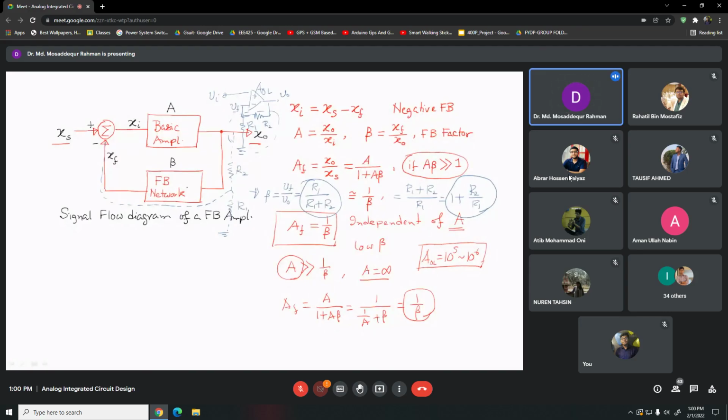So this all started with the development of the theory of the feedback amplifier or feedback technique, right? We need a basic amplifier with a very high gain. Now there are other requirements that need to be satisfied. One requirement is that at the input side, we need to take the difference between the source signal and our feedback signal, and that has to be precise.